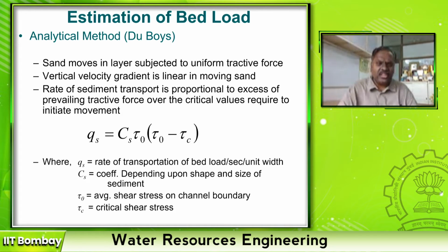It depends upon the shape and size of the sediments, as well as the shear stress of the channel boundary. If the channel boundary is very smooth, then my sediment rate will be larger. If my average shear stress is very large and the critical is also very large, then there will be less tractive force, so the sediment may not roll.